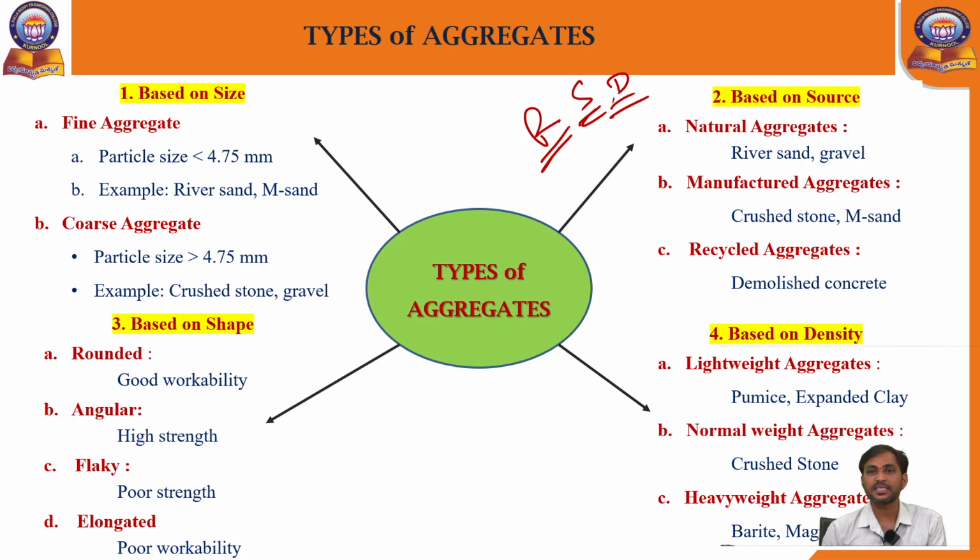But for the construction purpose, which sand do we have to use? For the entire construction process, we have to use the river sand. River sand is most important and most applicable for construction. Why? Because this river sand is free from any minerals and free from any contaminants, and the particle sizes of the river sand are standard. Coming to sea and desert sands, sea sand contains salt contaminants.